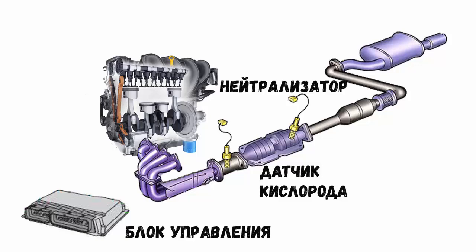Together with oxygen sensors, catalytic converters are used, the task of which is to reduce the emission of harmful substances into the atmosphere. An oxygen sensor that controls the composition of the mixture is installed in front of the catalyst. In accordance with Euro-3 standards, the operation of the catalyst itself must be monitored. Therefore, on machines with Euro-3, a second oxygen sensor is installed, but after the catalyst. It controls the efficiency of the converter.